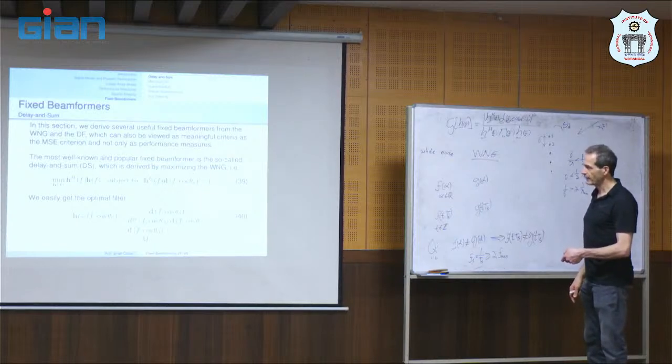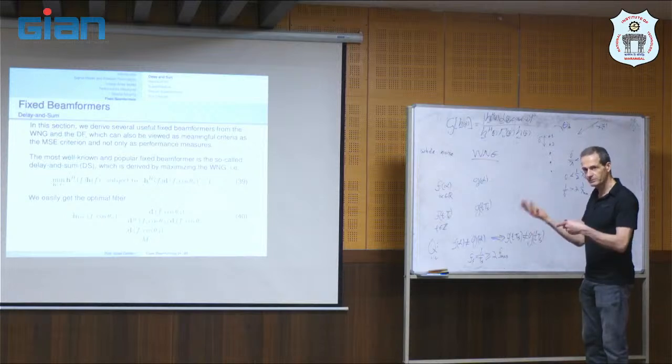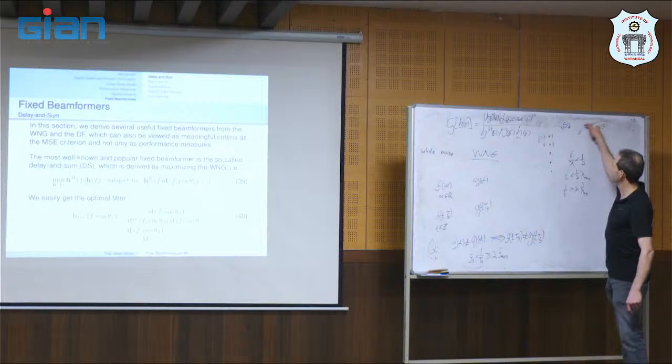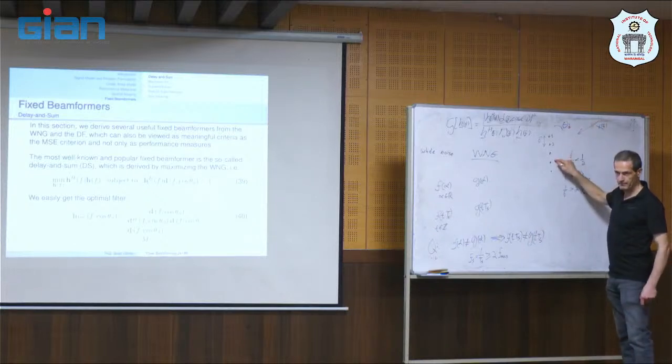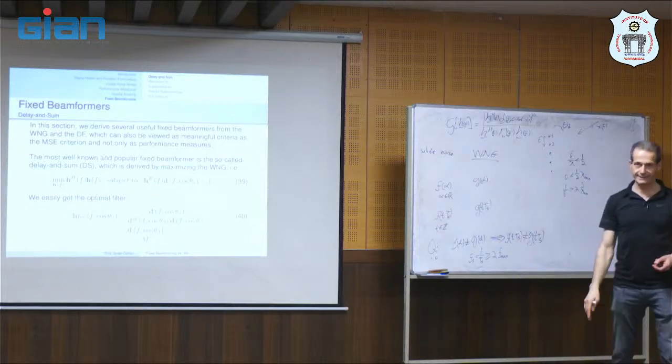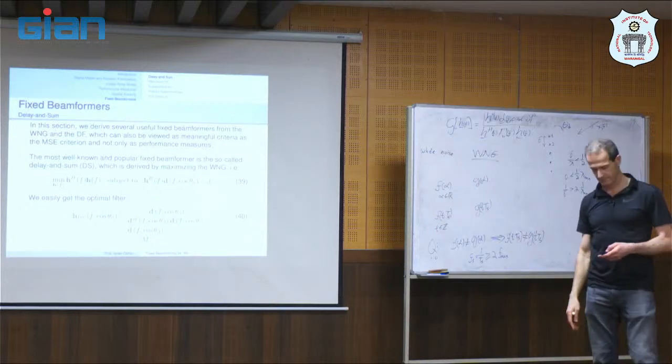This is a normalization factor. But if the beamformer is simply the steering vector, it means that it exactly compensates the delay for a signal that comes from theta D. That's why this is the delay and sum beamformer.